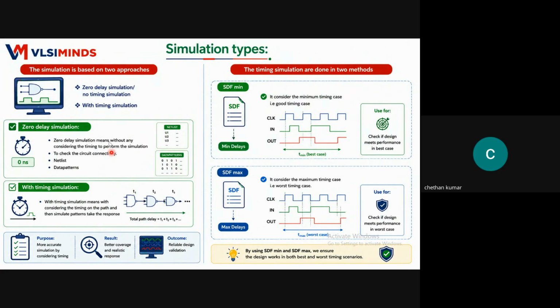For the zero delay, we can use the stuck-at patterns itself, but for timing simulations we have to go with TDF patterns, the transition delay patterns, which we have generated by considering which case we are doing, either the min corner or the max corner.